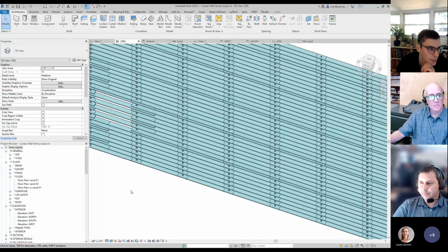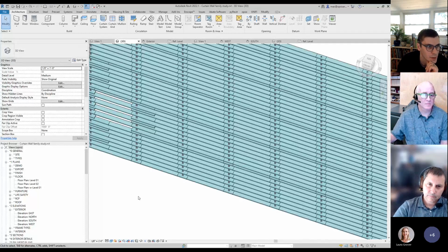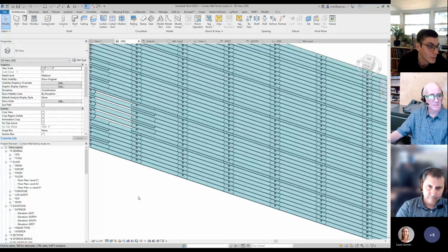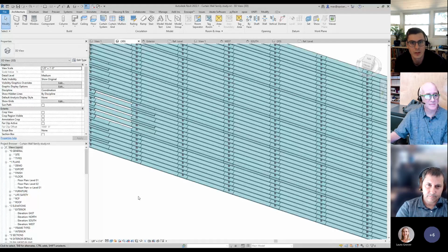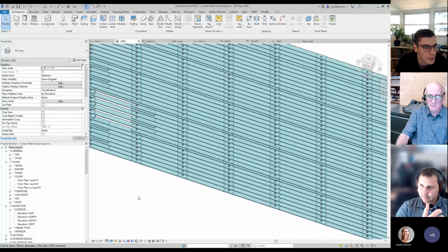And that's such a good point about all the elements. Revit obviously has a suggested way, like use a roof for a roof, but when you think about it, the roof has the ability to have a fascia. What can you use the fascia for? Maybe you're not just using it as a panel or a piece of wood. Maybe you're making sidewalks out of it and using it for the curb assembly. There are so many different ways to start to think about these elements, and understanding what comes in the package of each system family type and how you can use it to get across visually what you were trying to do.